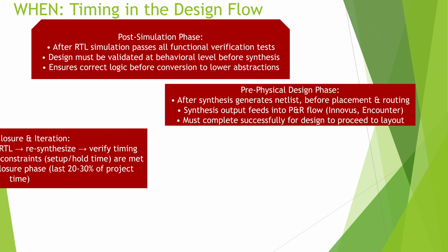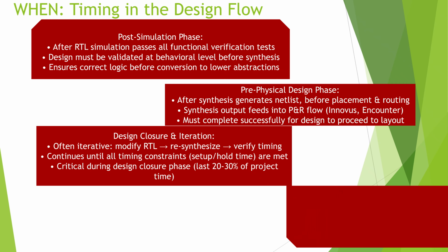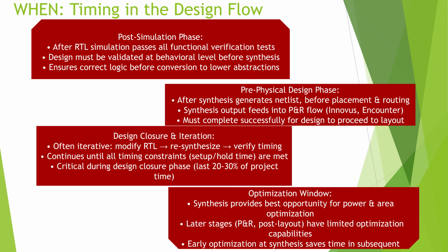And after synthesis, we keep iterating, adjust RTL or constraints, rerun synthesis, check timing and power, and repeat until we reach closure. Exactly. Especially near tape-out, this modify and resynthesize loop is very intense.